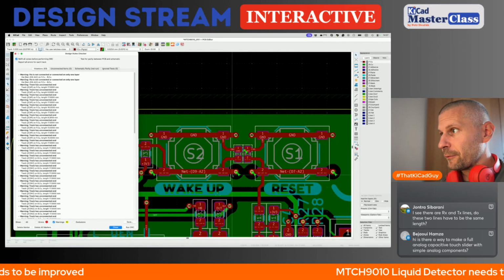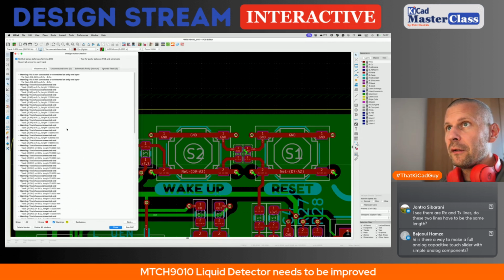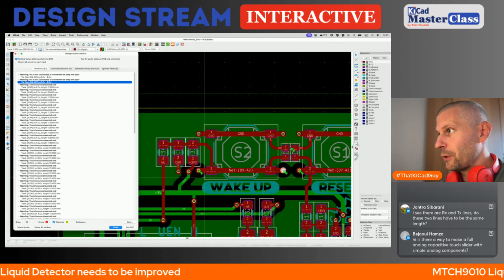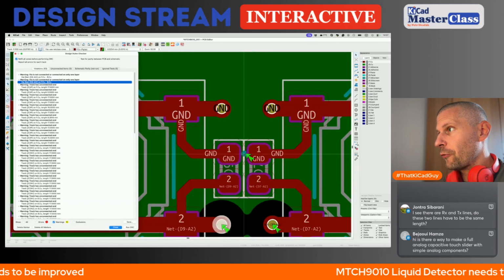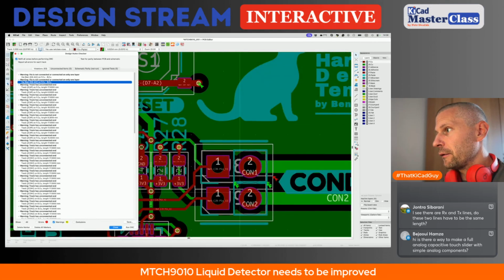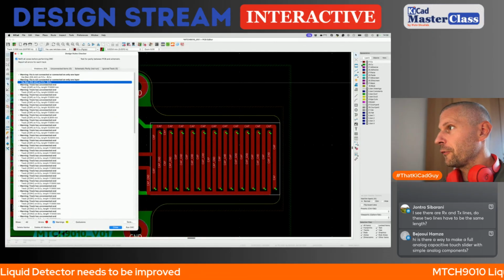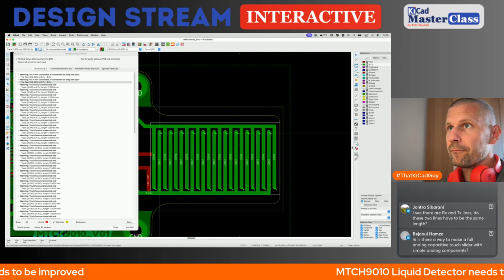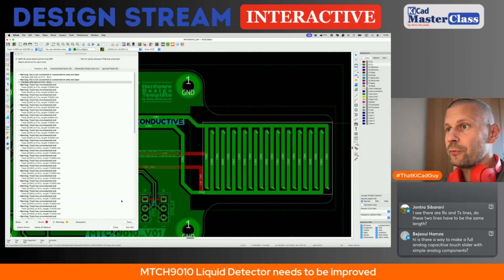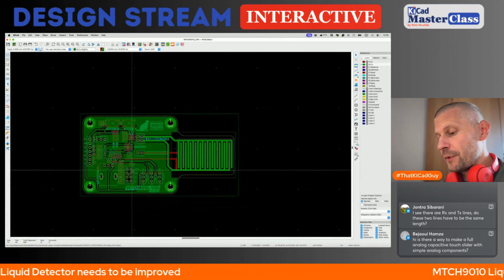Yes, we are connected on one track only. Yeah, like here. I explained why I do that and why this is not an issue. Overlapping silk screen, no problem, as well. And a myriad of warnings for the unconnected ends of the tracks, but this is our sensing segment, so we need it. So it seems that our PCB is fine.